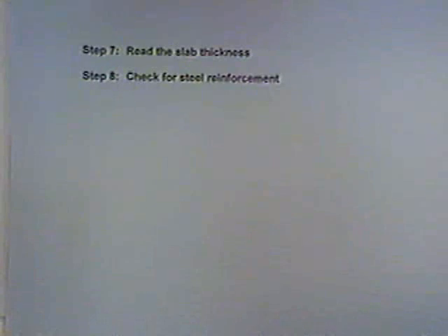Once you know those things, you would go to the chart at the bottom of page 1625 in your reference manual, or reading the slab thickness from figure 1614. And it says it's a design chart for a terminal serviceability index of 2.5. You know your equivalent loadings, you know what your working stress is, you come up to your turning line and go down, and you would come up with the thickness of the concrete that you would need.